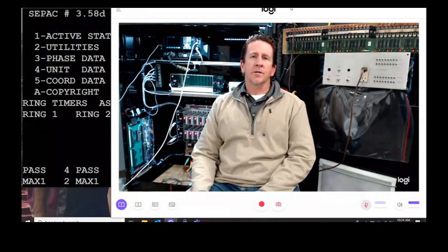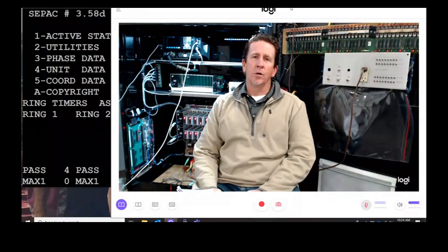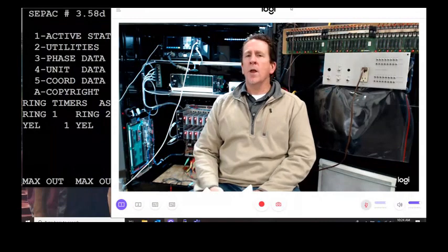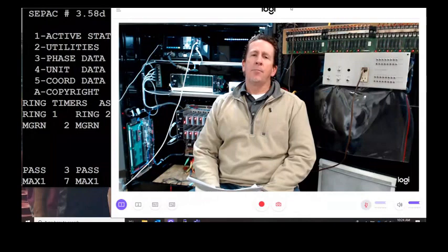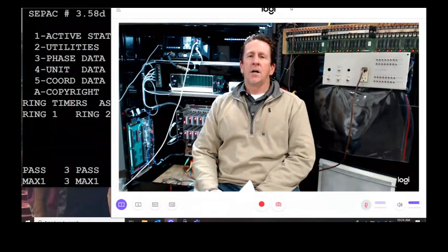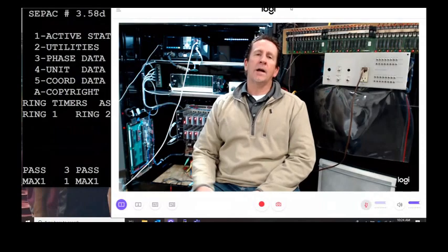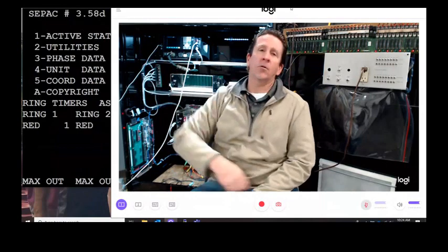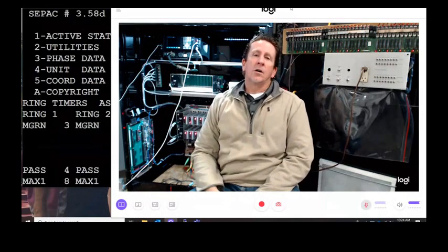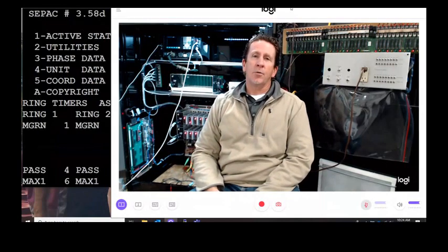Obviously we can burn things up. In TS2, there's a little less going on in the controller because we're doing it over the SDLC bus. Typically the port can get burned out, port 1, and we'll go over port 1 failures. If you go back to TS1, where we're using the A, B, and C connectors, those are all hardwired inputs and outputs.